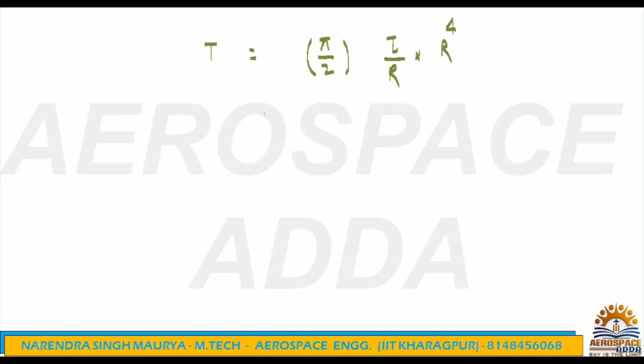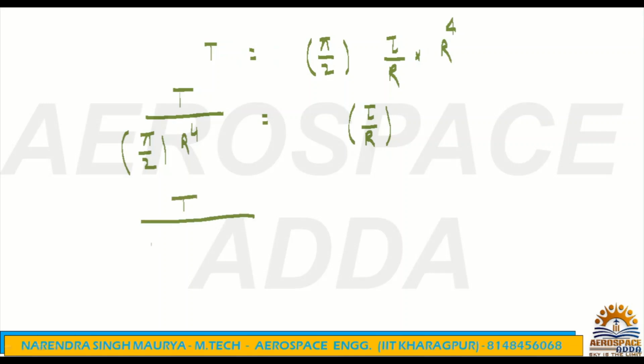So automatically, if you see, we have a tau by r. We just keep this side, and this side you can write tau divided by, everything will come in the denominator, pi by 2 and r to power 4. It comes like this. This is T and this is pi by 2. What is the radius in terms of diameter? It is diameter by 2 to power 4. We can write in this way also. It's nothing but tau by r. Just check what I am trying to do.